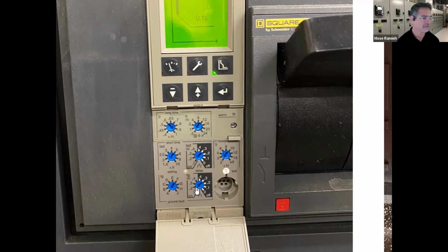Also very short time delay. And we can also point out that there were other things set at minimum. Short time is set at minimum, instantaneous is set at minimum. So from a reliability standpoint, this breaker was not set per a coordination study. I can tell you that just by looking at it. I don't even have to see the study to know that. Because once again, the short time, instantaneous, and ground fault in theory don't coordinate with breakers downstream, once again leading to their problem. So it's important that somebody check this.